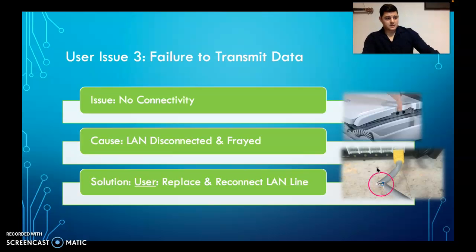And that moves us into our probable cause. So per 15-1 of our user manual, we know that it's most likely a connectivity issue. And there's 3 possible solutions to this issue depending on what kind of connectivity they're using. So whether it's wireless or plugged in, so a landline, those are the 2 main things. So in this case, we have to talk to the IT professionals to see what exactly the unit's pushing their data out on, and we confirm that it's a plug-in Ethernet cable, so the LAN cable.